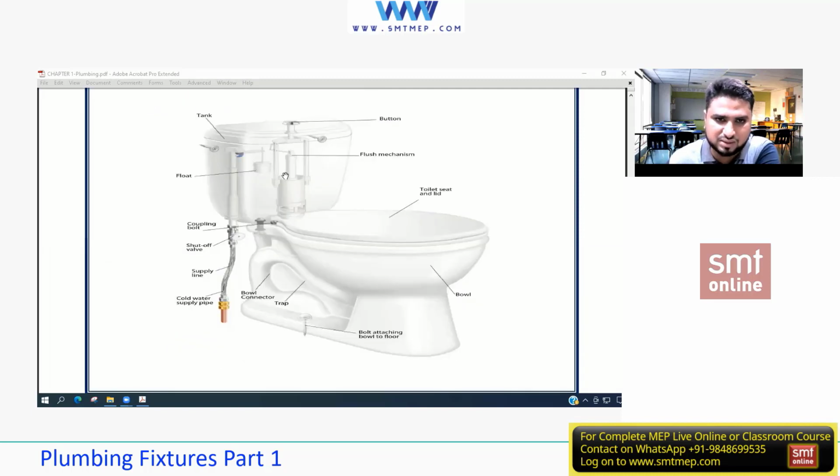This is only a WC over here; don't keep in mind that this is something else, we'll be seeing it later on. This bowl you're seeing is a WC, and this WC demands cold water. Why are we discussing these pictures? Because when we do the design, for example the load calculation for pipe sizing or routing, one should know what fixture demands what kind of water, hot or cold. Then I need to count the fixtures accordingly and proceed with the calculation as needed.